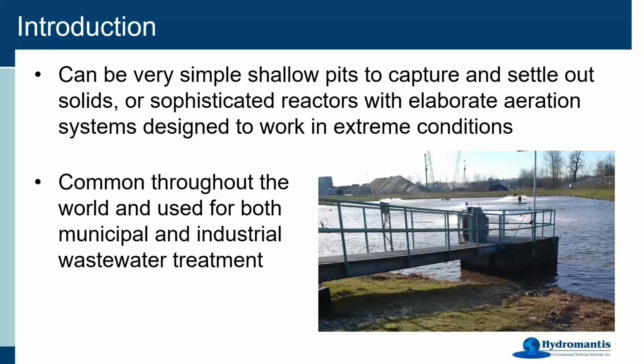The lagoons themselves can be really quite simple in terms of shallow pits that are really there just to do some polishing and maybe settle out some final solids. And as I mentioned, some of them can have very sophisticated aeration systems, on par with what you would find in a full-scale BNR plant. And these are common throughout the world, and they're used in both the municipal and industrial wastewater treatment world.